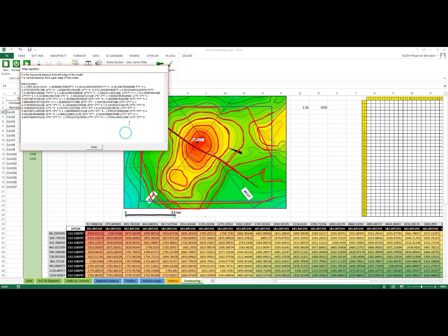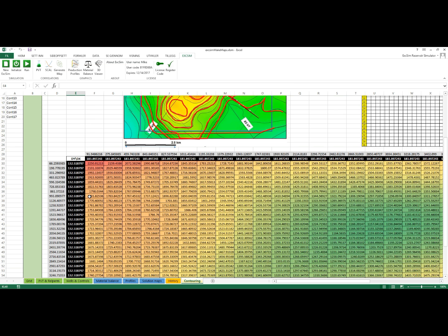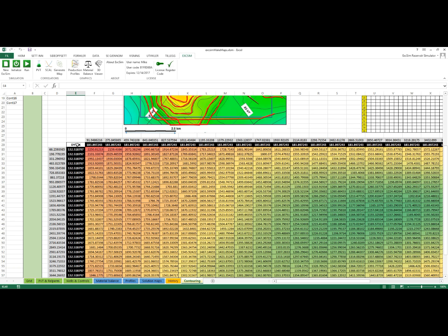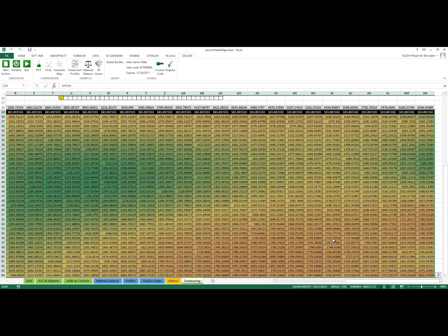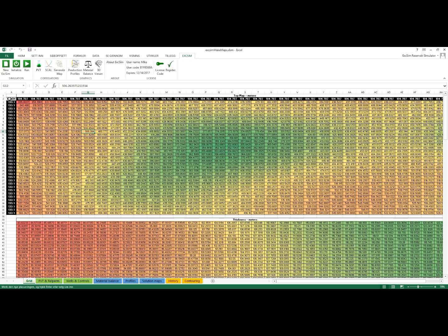It's a 2D polynomial with the highest powers x to the 5th and y to the 5th, but every power lower than that is also here. And the map is displayed here. So I'm going to copy this whole 35 by 35 map and go to the grid section and just paste it there.